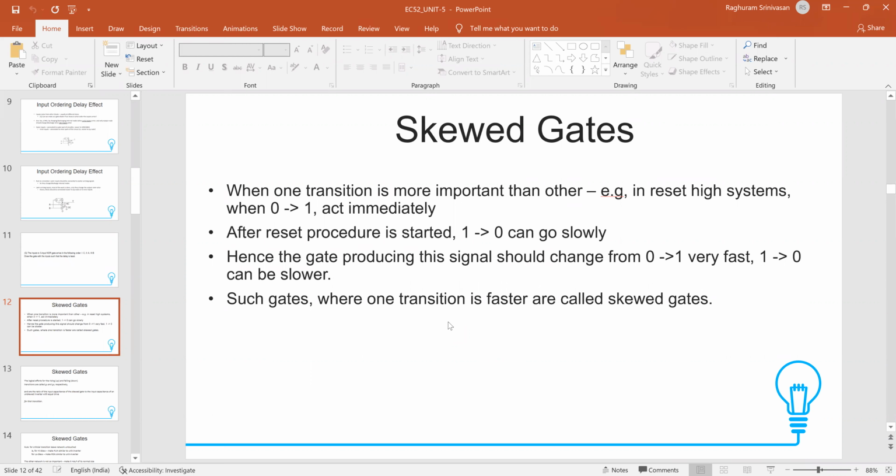That is the idea we have used for all the gates that we have designed, including the compound gates, including the NAND gate, NOR gate, etc. For all the gates, the rule that we followed to get 2:1 for the inverter, then 4:4:4:4 for the NAND gate, etc., is that the NMOS and PMOS networks, not the individual transistors, should have the same resistance, which means that the output delays TPHL and TPLH will be the same.